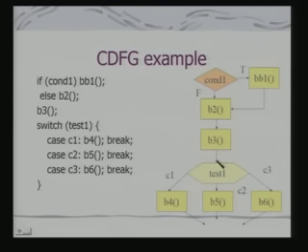So, I can represent these as a control data flow graph. Now, each of these are nothing but functions. Corresponding to the functions, I can again have a CDFG, and that CDFG will replace this function. And if I have a simple assignment, then that assignment block can be modeled as a data flow graph.